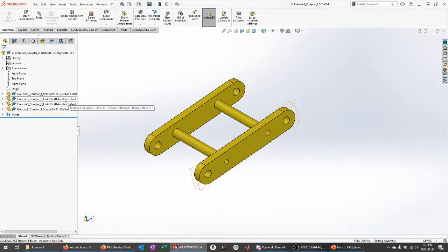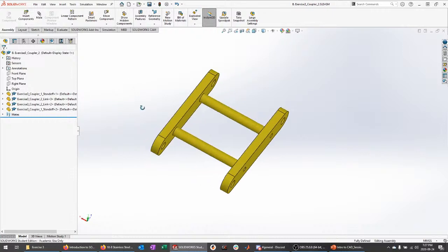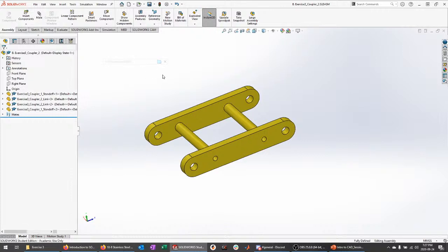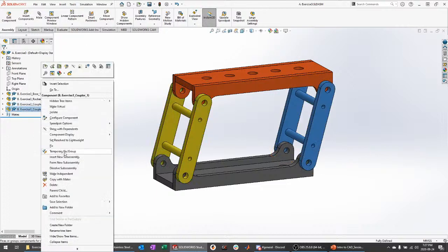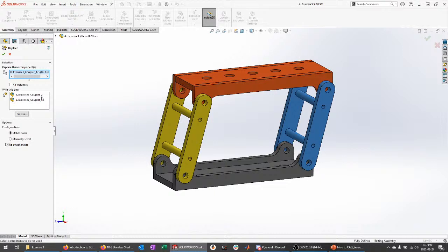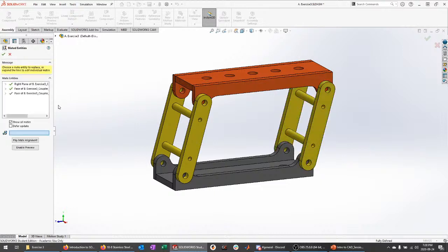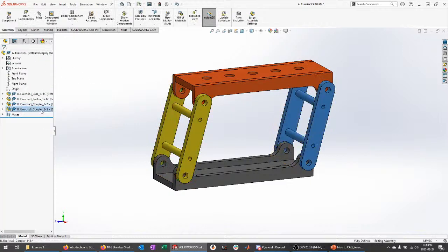So what we've effectively done here is replaced the link, both metaphorically and literally. We've replaced the link in SOLIDWORKS with a new copy of the link, the part. That's a bit confusing, I recognize. All right, so we now have this new subassembly. If we go back to the master assembly, I'm going to take one of these couplers and replace it with our new subassembly. And again, since nothing has actually changed yet, all of those links are fine. So now these are not two instances of the same subassembly, they're two separate subassemblies.